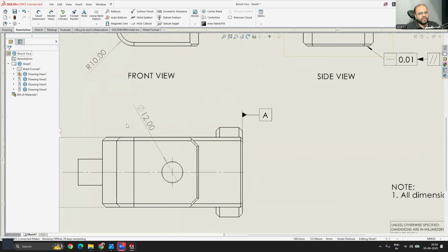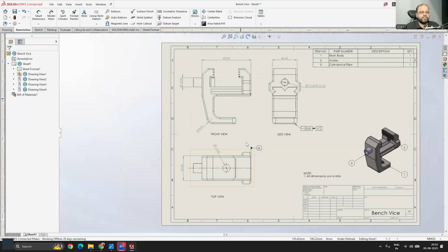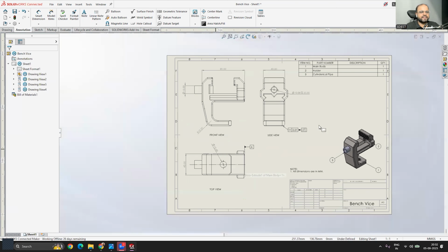In your drawing or any part, there could be multiple datums, but that depends upon what kind of machining process you're going to use to machine your part, what your machine tolerance is, and those things the vendors who will machine your part will be able to provide, right? So that way you can start adding features.